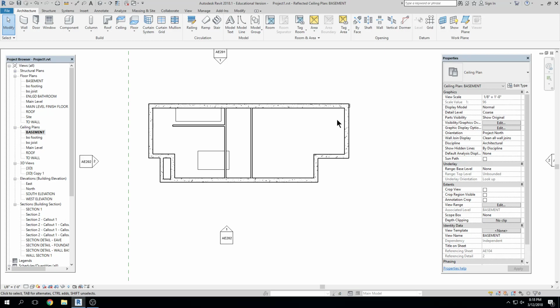So that's one way of thinking about a ceiling. You could take your floor assembly and add the floor joist, add all of the layers of the floor on top, and then add gypsum board to the bottom of your floor joist, and that would be a ceiling, right? You could think about it the same way with a ceiling tacked to the bottom of your trusses. That could be gypsum board on the underside of a truss, which isn't a floor plate, but it's a structure.